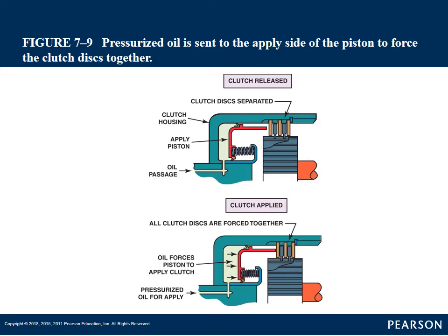If you look on the outer side of that apply piston, you see a little black, V-shaped thing in this picture. You'll see it on the outside and the inside of that red apply piston. Those are your lip seals. That keeps fluid pressure from moving past the piston. If you lose fluid pressure, the piston doesn't apply, and either you don't get a change of gear, or it tries to apply but not very tight, and then the clutch pack slips.